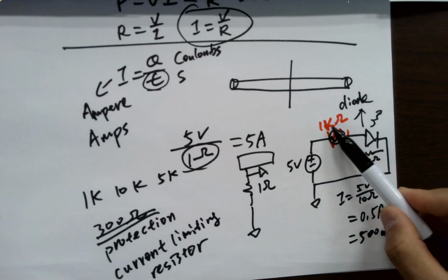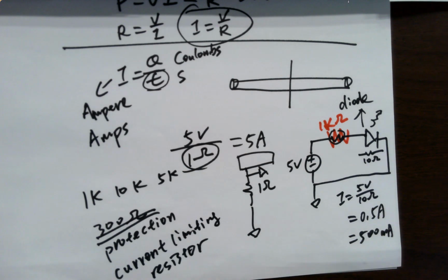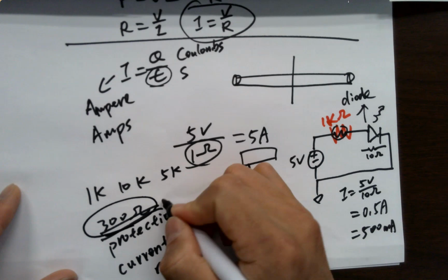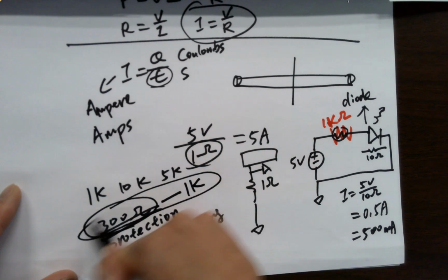So what if you put a 1K resistor and it's too dim? What do you want to do for that? Use a lower resistor. So what's the resistance you want to use? How many volts do we want to send to the LED? We usually don't consider that. How many amps, how much current, right? So just look at the paper. What's the range of the LED going to use? Usually for low voltage stuff, digital stuff, like I said, here, that's a sweet range to use.